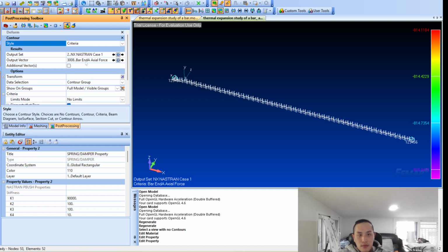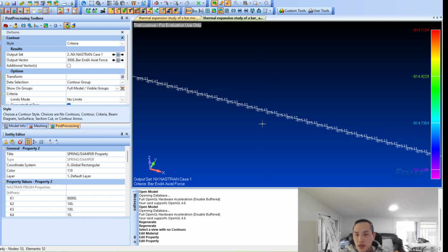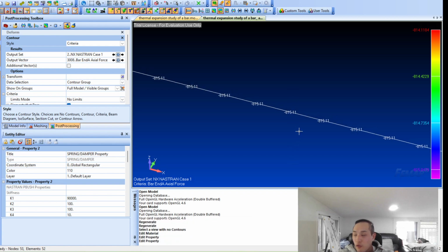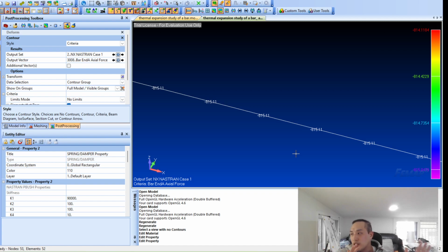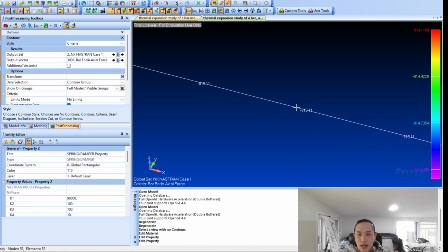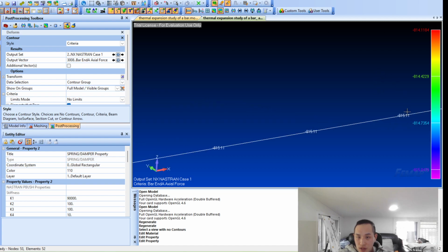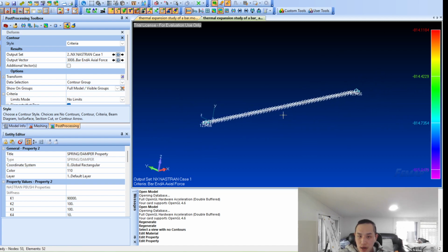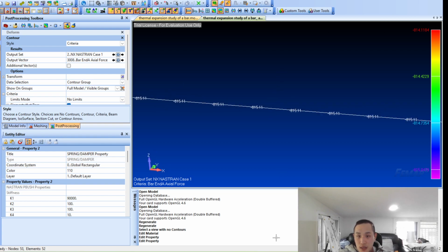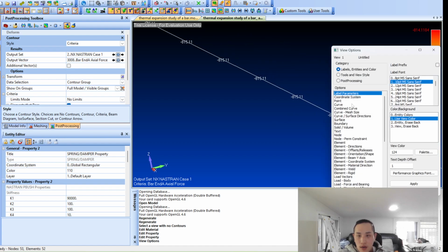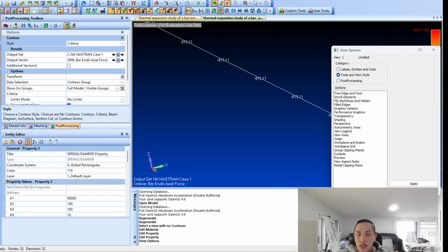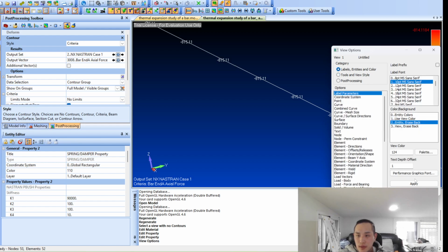If you guys can recall springs in series, you will definitely recognize that the force in this bar, relative to what we saw in the previous example for fixed, it definitely should be lower, but how much lower, right? And so in this particular example, when adding those springs on both sides, added a spring here, added a spring here, 90,000 pounds per inch, just an idealization, the internal force within the bar comes out to be 815 pounds. Okay.